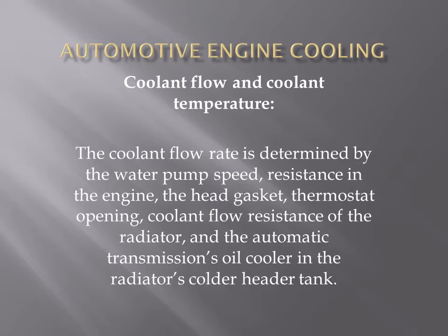Coolant flow and coolant temperature. The coolant flow rate is determined by the water pump speed, resistance in the engine, the head gasket, thermostat opening, coolant flow resistance of the radiator, and the automatic transmission's oil cooler in the radiator's colder header tank.